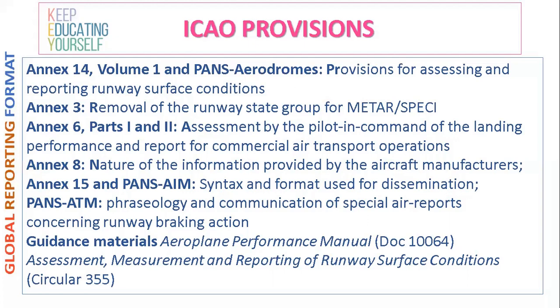Then there are some changes in PANS ATM Doc 4444. Definitions have been changed. Reporting of operational and meteorological information has changed. Contents of special air reports have changed. And then runway braking action not as good as reported, this section is also added there. Forwarding of braking action information when special air reports are received by voice communication has been added here. And these reports have to be passed without delay to the airport operator by ATC. Then essential information on aerodrome conditions, terms used for runway surface conditions. So all these things have been changed.